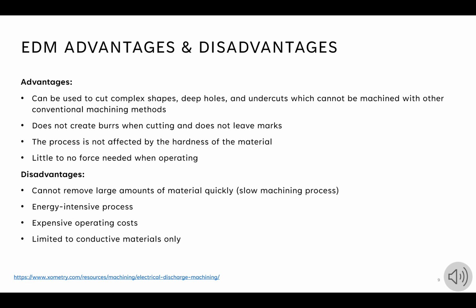human error. Some disadvantages include that you cannot remove large amounts of material quickly, so if you are manufacturing something that is time restricted, EDM is limited to those restraints. It is an energy intensive process, which means that it can be harmful to the environment and leave a carbon footprint. It's an expensive operating cost and it's limited to conductive materials only.